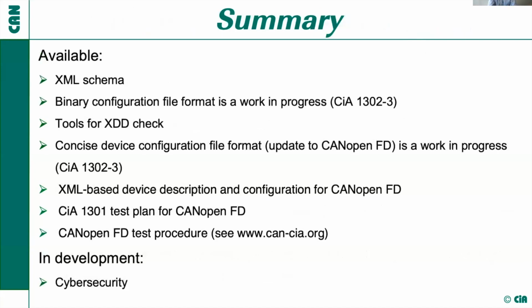Finally, on what is available: we use only XML-based device description, no textual format description, as we agreed. Then the binary configuration file format is in development. Tools for XDD check are available. Tools for CANopen FD, for reading CANopen FD messages, are also available on the market.